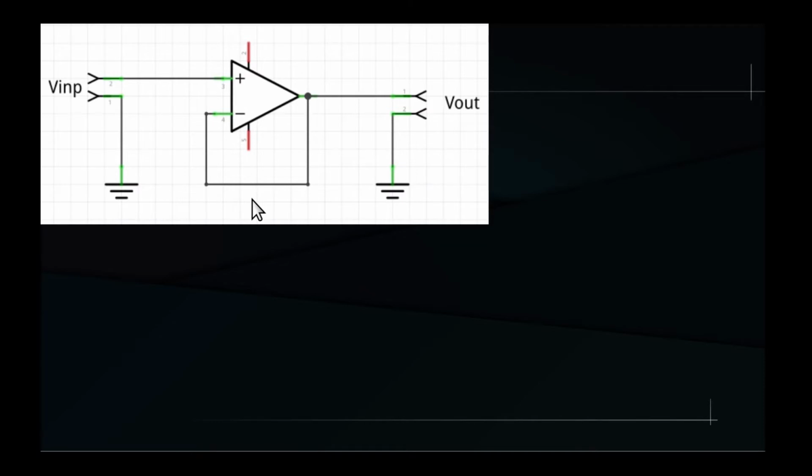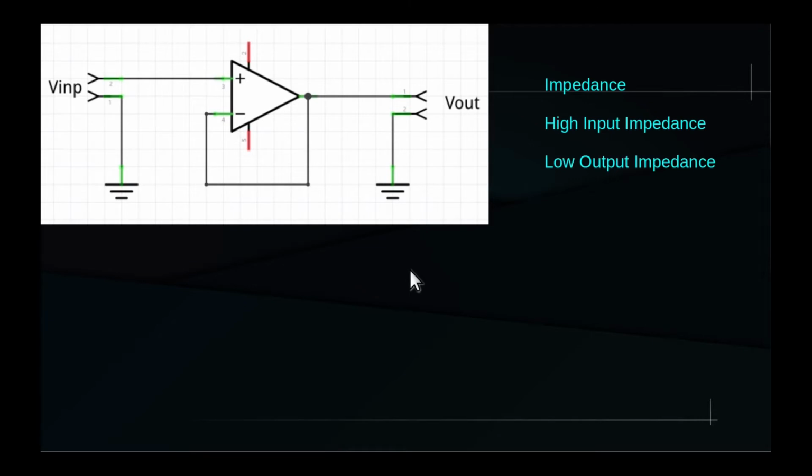So basically, whatever is the signal applied to the input, we find exactly the same signal at the output. Now you may ask, why do we care? We already had that signal, why don't you use that directly? Well, the answer is impedance. When we put a voltage follower in between two other circuits, we do what we call an impedance adaptation.